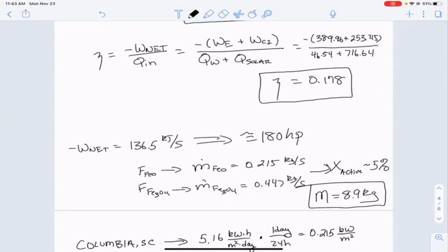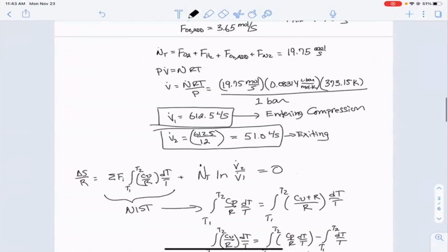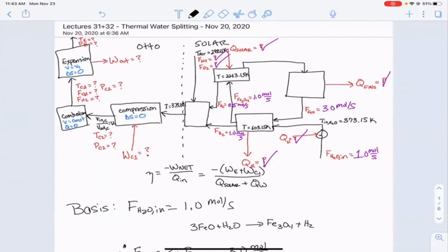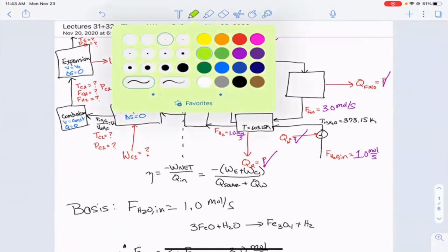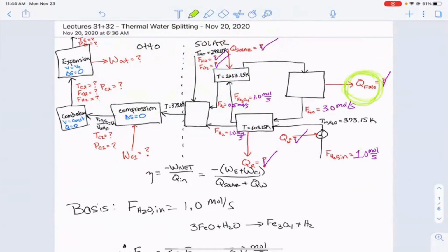The other thing while we're talking about efficiency is how do we increase the efficiency, right? So if we look at the overall process here, there's a couple of ways that I could think of to do this. One thing is that it seems silly to me that you would have heat that you have to remove from these fins, and you would separately heat the water, right? That you'd have some other mechanism. If I were going to do this, I would actually just feed this into there, right? And exchange heat to preheat the water. And that would reduce the amount of heat you had to remove in the fins. And it would eliminate this from our efficiency calculation. So we'll take a look at that in a second.